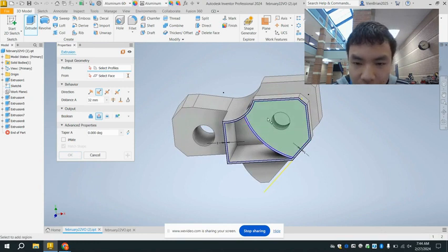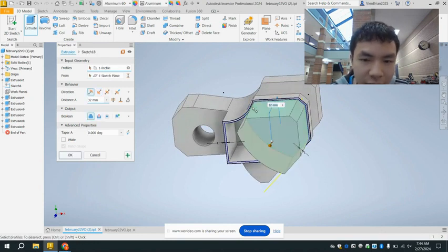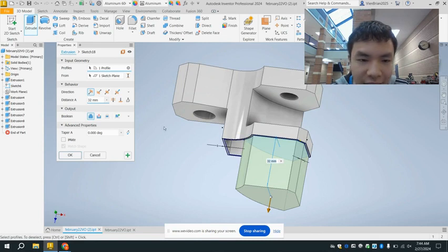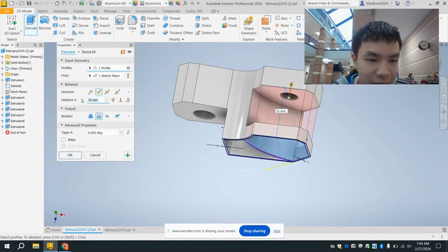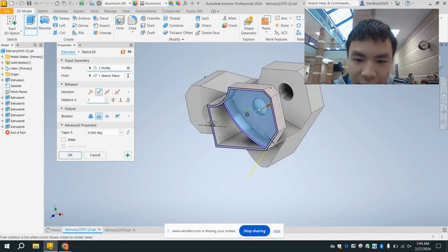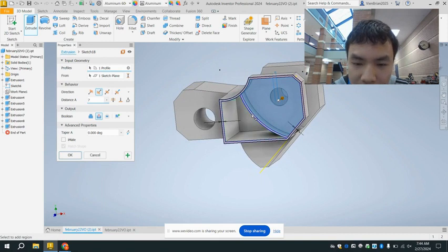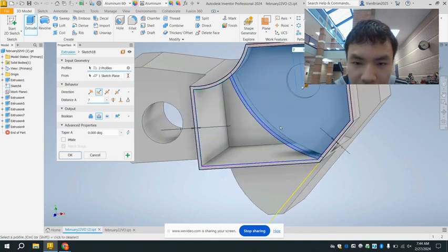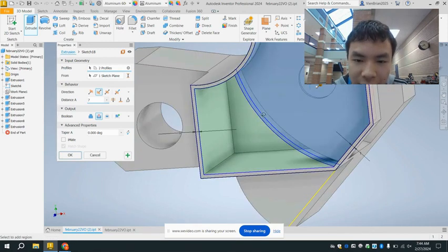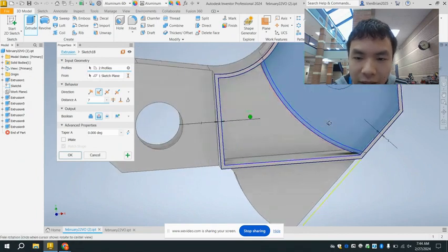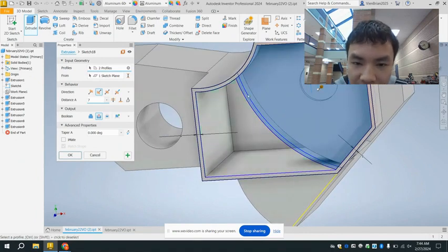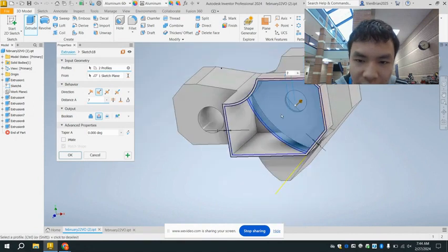And now you can extrude this part. And obviously, if this side is 8, then you can't extrude 8 or more. So it can't be 32. So it has to be like 7 maybe. And you see the circle right here. And you can extrude this part. There we go. Make sure, because this is offset for this piece to not get deleted, right? So make sure you select that little sliver right there that we have remaining. And you click on 7 and you click OK.